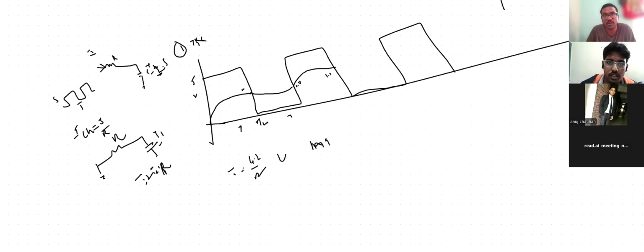The 2.5, when you take duty 50%. Yes, sir, duty 50%. The 2.5 value is decided by the duty of the square wave, right? Yes, sir. Because duty cycle means on time by total time. Correct. That will be depending on RCs again? No, no, no. I am defining duty, right? Input I will define. Why will it be decided by RC? I will decide my input.